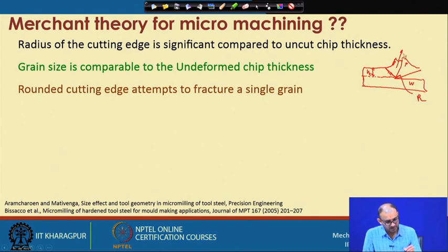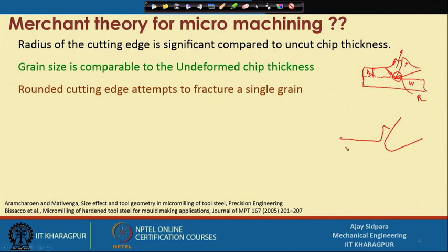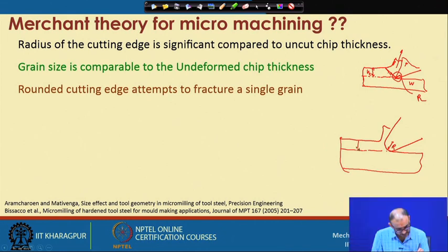So, this is in terms of conventional machining, but we have to magnify this area to understand what is going to happen in the micro machining case. So, now let us say this is the actual case of the cutting tool, and now our chip will be something like this. This is the machined surface, this is the bottom part, and this is the chip. Now, this is our R and this is our HC. Now, many times whatever R is there, sometimes we have to cut a very small amount of material, because the process is very slow, and we also have to understand that tool life is very short if your depth of cut is very large. So, generally we work with a very small HC, maybe starting from 10 micron to 100 micron. At that time your R will also be very small.